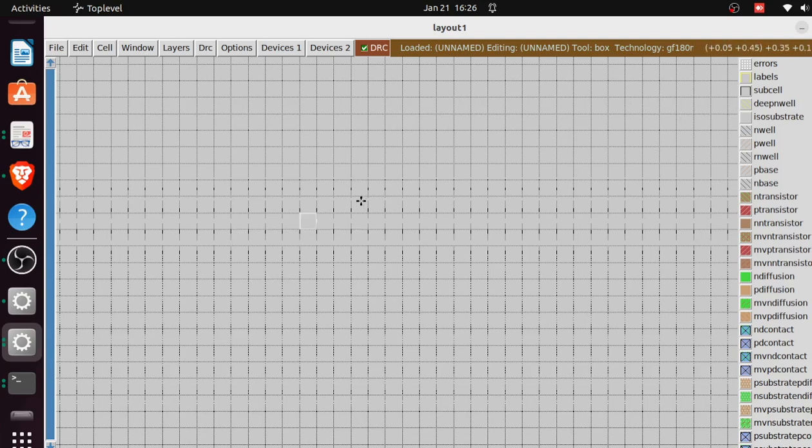So if I want to draw a box up to this point here, after positioning the cursor there, I just right click, then the box would be as big as that. Then again, if I want to increase it further, you can just go to the new location and still right click. You don't left click, you right click.